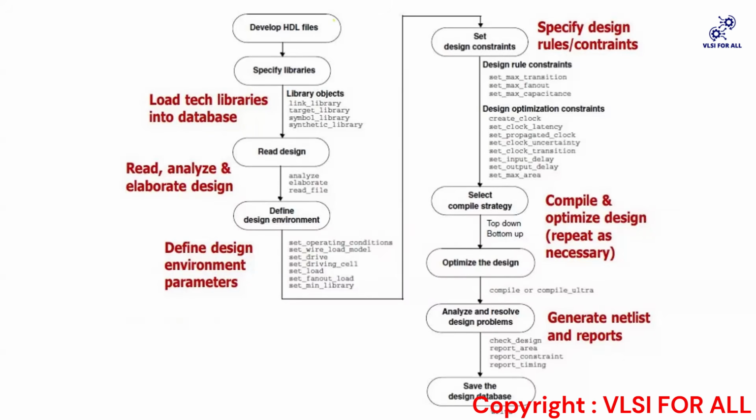After this, of course, we need to save the design also. Till here, you will try to fix any violations and also optimize PPA, that is power, performance, and area. After this, you need to save your design. For saving your design, you can use the write command with hyphen format. I'm telling you the syntax. If it's Verilog, you can just type Verilog, then hyphen hierarchy, hyphen output, and you can give a name. This is the syntax of the write command. You can save your design.